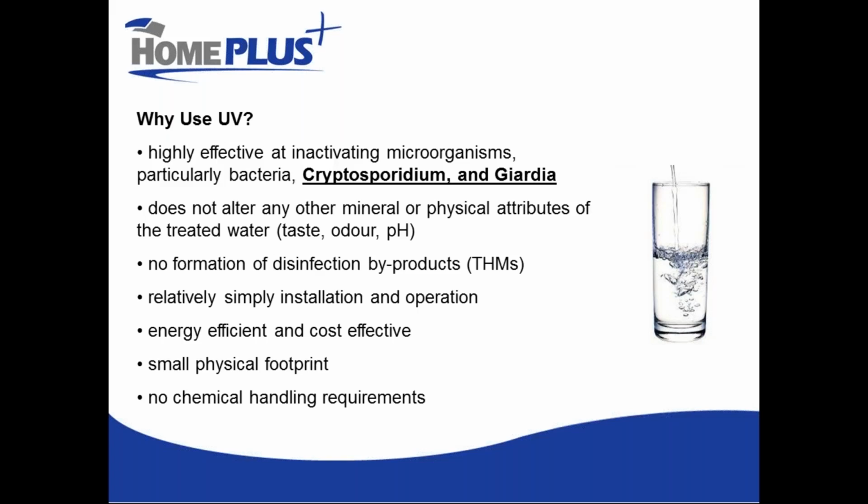Some of you that have organic matter in your water, when you chlorinate, you may be faced with challenges of byproduct chemicals like trihalomethanes or haloacetic acids forming. We don't have to worry about that with ultraviolet light. It's fairly simple to install and operate. It's energy efficient and cost effective. It's physically quite small, and there's no chemical handling requirements.